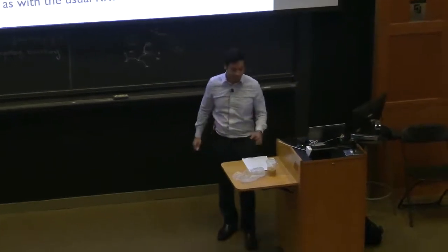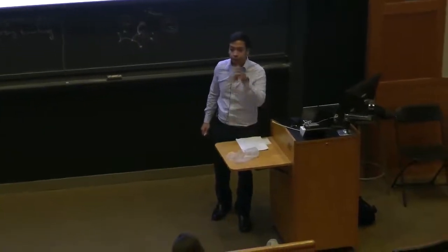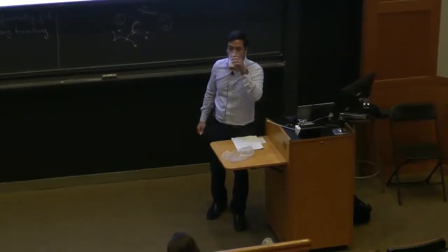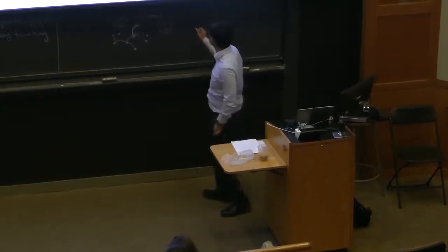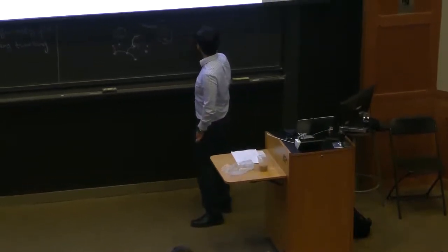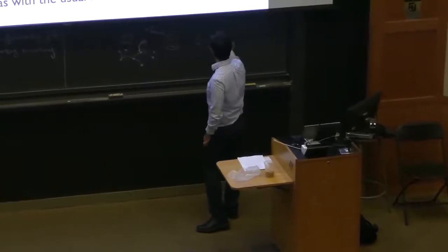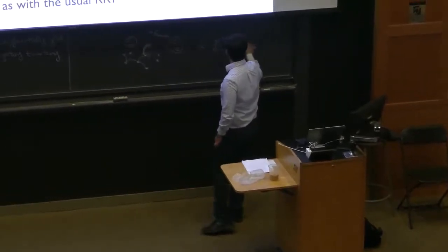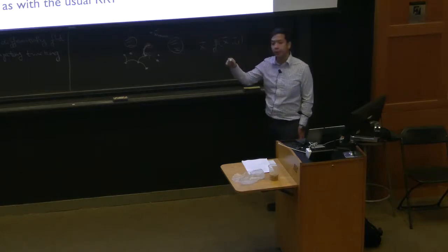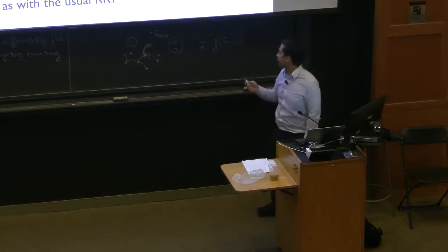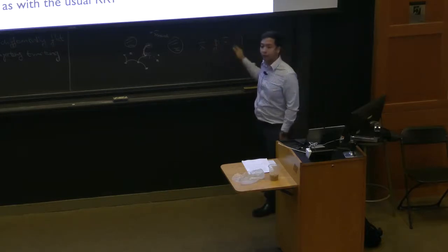Question? What about this algorithm tells us that the trajectory from sampling the control inputs isn't going to be a line segment, like when you're drawing? Yeah, so that depends on the dynamics of the system. If you just have some arbitrary dynamics, x dot equals f of x and u, whether the trajectory that you end up following is a line segment or not just depends on the exact form of the dynamics, so the exact form of f.